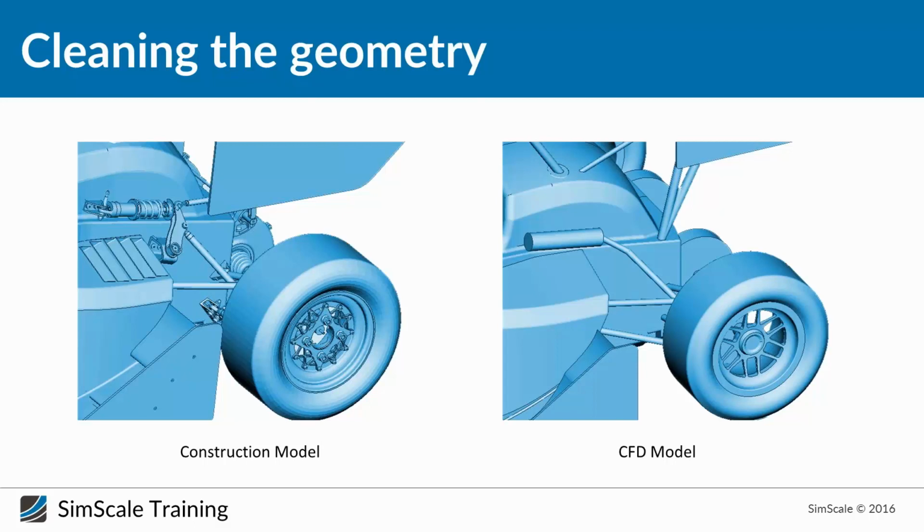So it's better, in the first step of your design or your optimization process, to keep it as simple as possible. Then maybe as a last step, you can add some details that will not affect your mesh quality. Because if you add details, then you will end up with bad cells and bad quality mesh. It's better to keep it really simple.